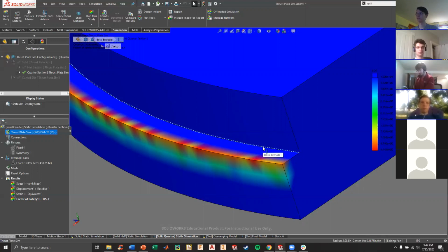So I tried the fillets, but this is a super small lip. So the fillet sizes we're talking about, they're like 0.02 or something radius. So it's still a singularity, just as a result of kind of how we fixtured this.